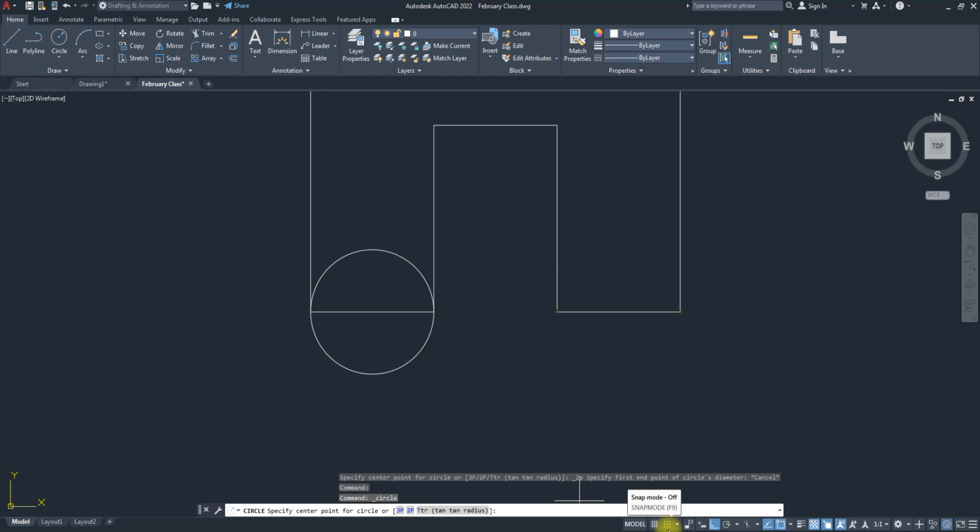So this is an object. I'm able to snap to the end point of this object, or to the end point of this object, or to the center point of this object, or to the tangential point of this object. Notice it relates to this object. So it's because another snap is on by default. If that snap wasn't on, believe me, you won't be able to snap to those things, and you will just assume. So let me turn off that snap.